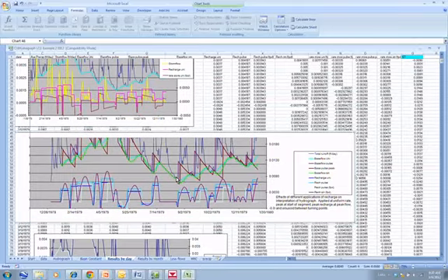Up here, if we take a look at the base flow, we see some more differences. The base flow with the uniform distribution is the blue. That's what we have been using. But you can see that these two brown lines are pulse increases in the base flow, and this green line is the sinusoidal. So you can see that when we assume these different ways that the recharge is applied, we get some pretty different results for the base flow.